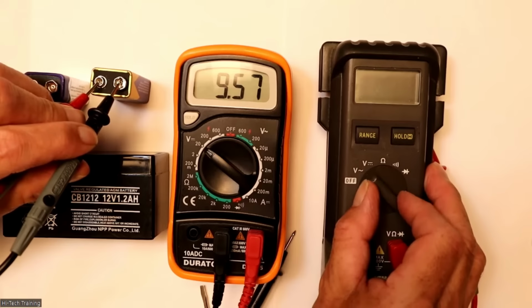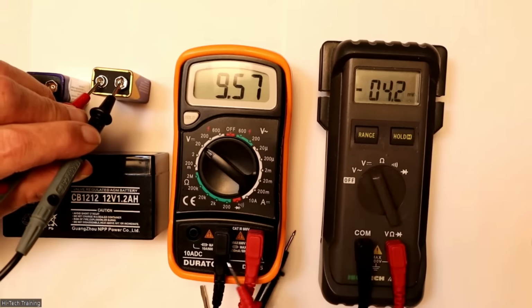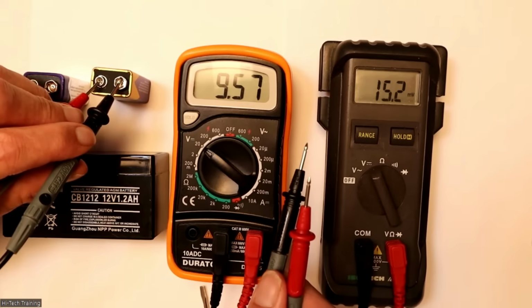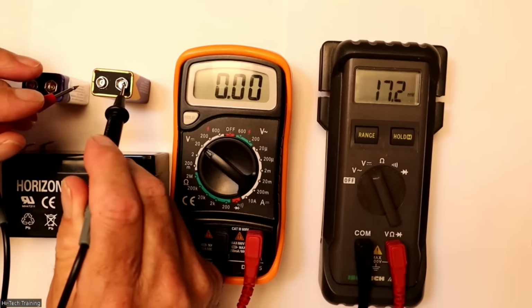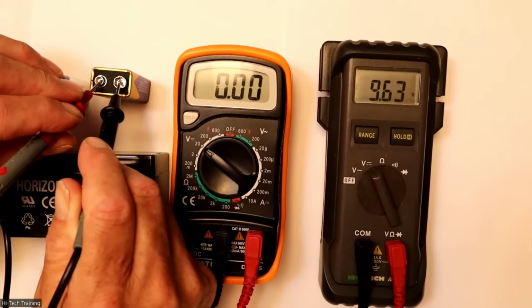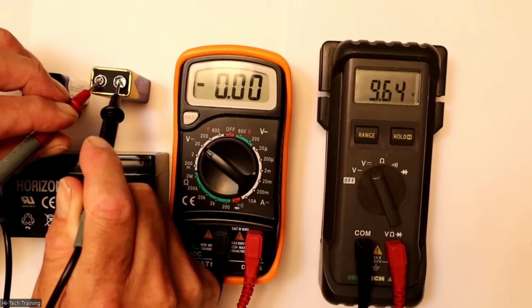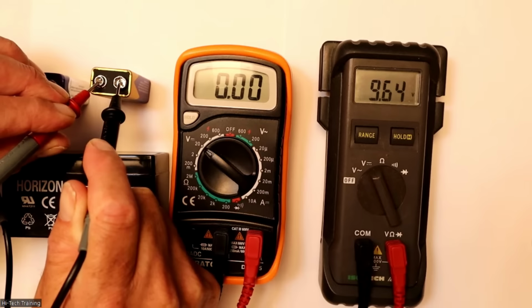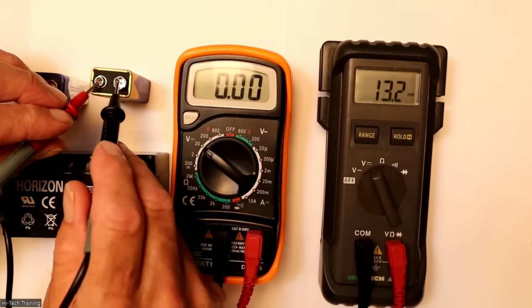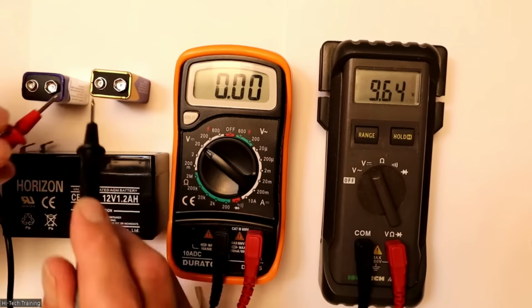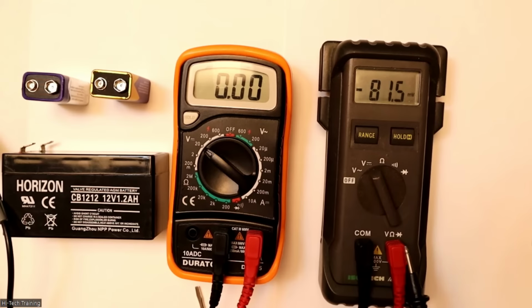We can go on to our digital meter here as well and use the other probes there. If we want to read the same battery there, so we'll see how we're doing on this one. So they'll probably read a little bit off, but fairly similar, but 9.64. Again, they'll always be a little bit off, but reasonably close together. And on this one, you don't need to select the range, just go onto your DC volts range and that's it. So it's very easy to do.